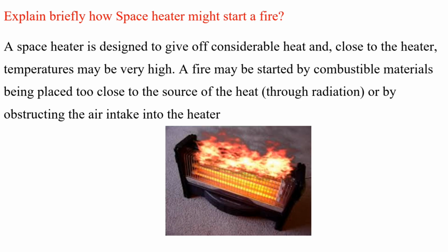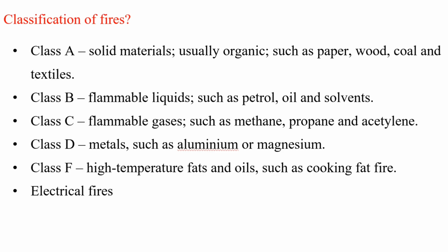Explain briefly how a space heater might start a fire. A space heater is designed to give off considerable heat and, close to the heater, temperatures may be very high. A fire may be started by combustible materials being placed too close to the source of the heat, through radiation, or by obstructing the air intake into the heater.